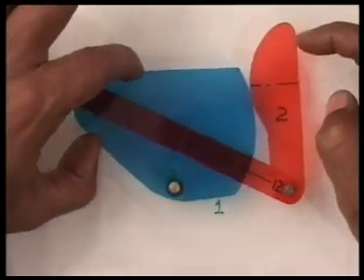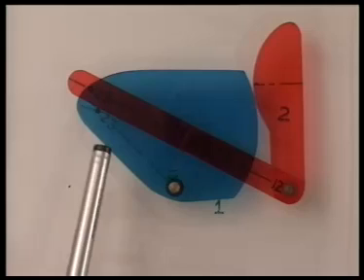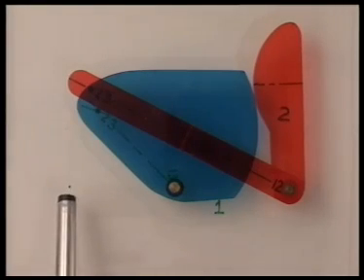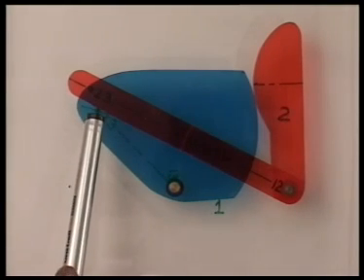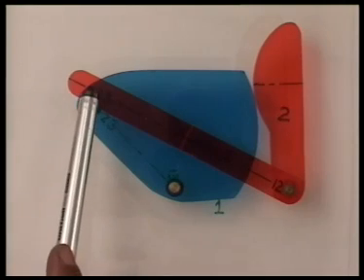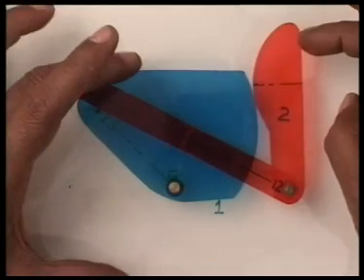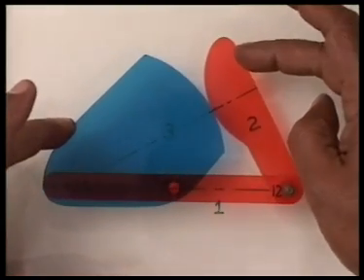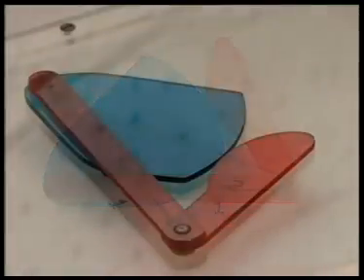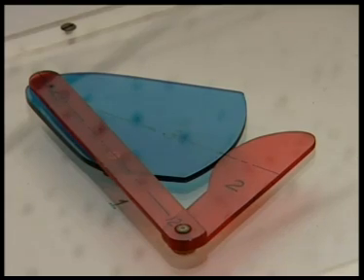However, when they have moved a lot, as we see, that point 2,3, which was here, as a point of body 3 has come here and as a point on body 2 has come here. I hope this clears both the concept of relative instantaneous center and the application of the Aronhold-Kennedy theorem, which we shall continue subsequently.